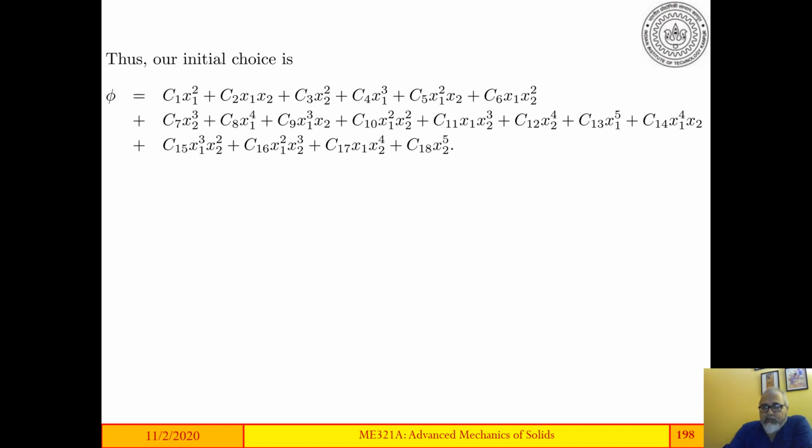And of the boundary conditions, we may have more boundary conditions than there are constants. So it is going to be an overdetermined or underdetermined problem, but you have to make sure that all the boundary conditions are satisfied. Remember, we have two sets of boundary conditions on the vertical edges, which are weak boundary conditions. So they have to be satisfied in a weak sense. They will not be satisfied in a point to point manner, but they have to be satisfied in order for me to claim that I have got a solution to this problem.